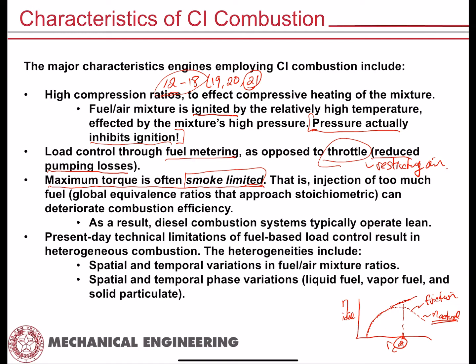So the first fuel that's injected ignites, it raises the temperature of the mixture as you're injecting more and more fuel into the cylinder, okay? And eventually your in-cylinder mixture temperature gets so high that the last droplets of fuel that you inject don't have enough time to undergo all the physical processes that they need to burn cleanly.